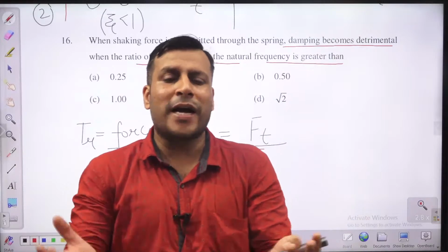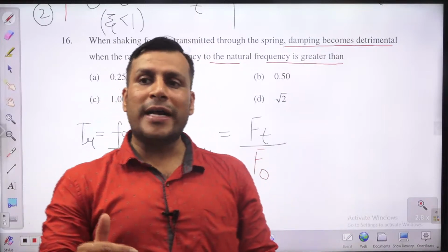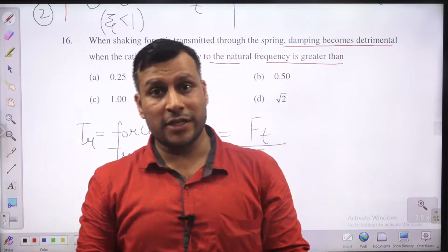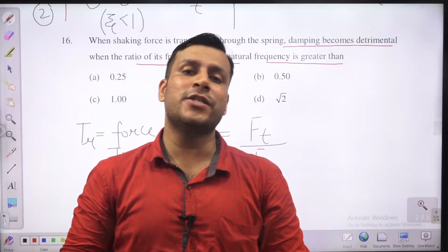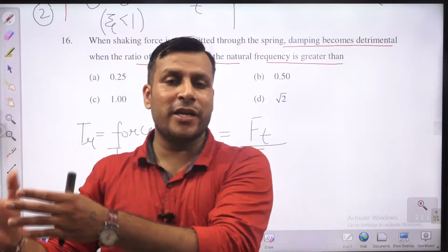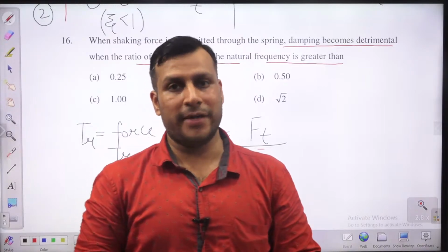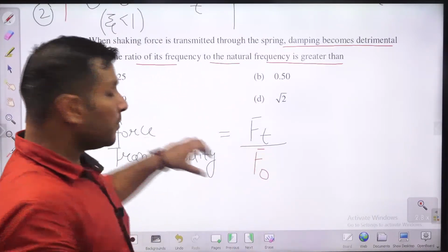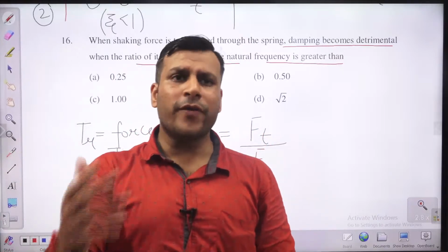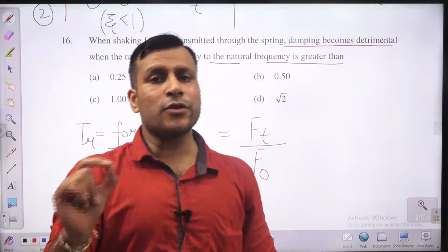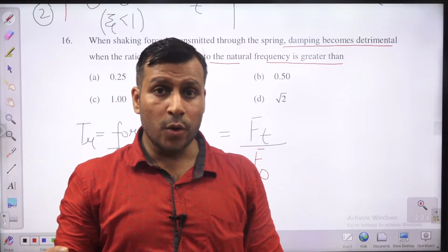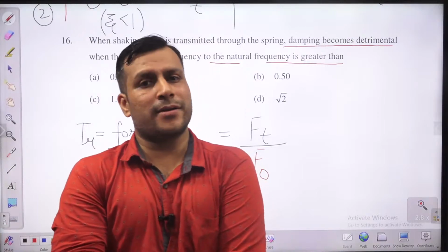That's why we always provide some kind of isolation to restrict the transfer of vibrations from the machine to the foundation. Because if vibrations go to the foundation, then surely whatever is on that foundation, any other machinery or component, is also going to vibrate. So there is a term which tells us about the effectiveness of the isolation. How effective is the isolation? That is measured by one parameter known as force transmissibility, or the transmissibility factor.